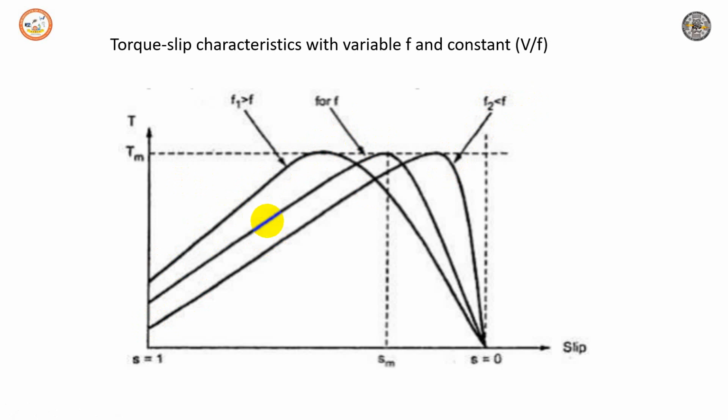So we can increase and decrease the supply frequency above and below normal in a three-phase induction motor using this arrangement. The only disadvantage is that the supply obtained cannot be used to supply other devices which require constant voltage. So we should have an individual scheme for each separate motor, which is most costly.